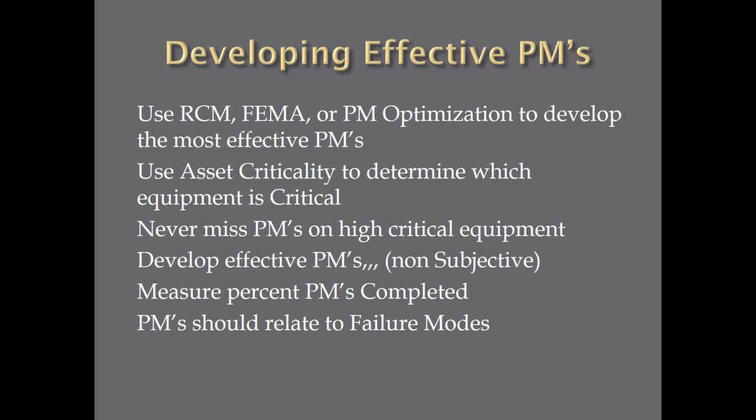Always measure the percent of PMs completed. I go through food and pharmaceutical plants where they say, well, I complete 99% of my PMs. Well, in studies I've done, they complete about 50% of their PMs. But they report 99 because that's what the audits recommend or require.